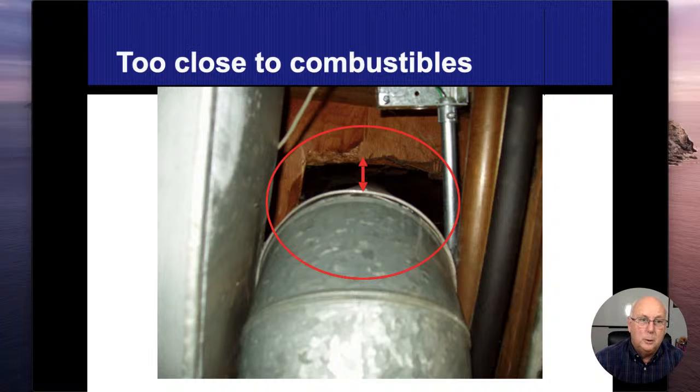All right, they're there to be overly cautious, overly protective. When they set up these numbers and these clearances, it's not that, well, we want to reduce the chances of a house catching on fire. No, we want to make a logical clearance distance where there won't be any chance that a house will catch on fire. So because of that, I'm kind of a stickler when it comes to these things. Anytime I see combustible materials such as the refrigerant lines, non-metallic cable wiring that comes in there, any sort of insulation that could be anywhere, wood structures of the material, if I'm within 6 inches, it's getting photographed, it's getting documented, it's going in our report. All right, that's my 2 cents.